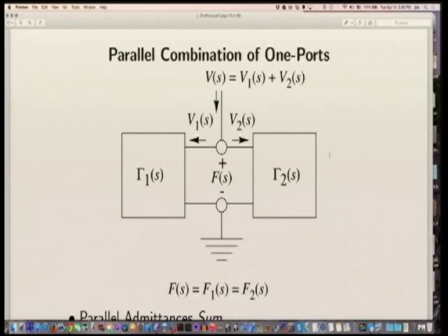So these are two ports that have been connected together and they have two different impedances. So that means that if some force, velocity, or voltage is being applied to this, we'll see these as terminating impedances for a traveling wave. And that traveling wave is going to scatter based on the impedance seen there. And so wave digital filters are kind of on the next level.